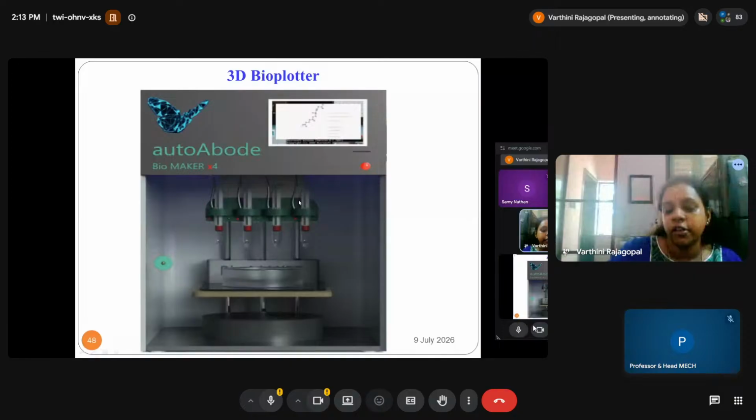I'll show you that. We actually made this nose using RTV silicone. This is not made for... it was made for robotic anatomy, soft robotics. We tried printing it, and after curing it was very much flexible. So we have a paste-based extruder. In this paste-based extruder, we had RTV silicone, that is 7071 grade raw material. This injection-based, paste-based material was extruded layer by layer, and then we built this one. So this one was our work.